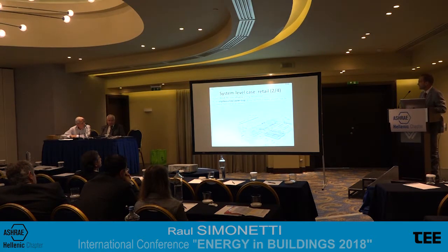If you break up this cross-influence between the display cabinets and make them independent from each other, then you can get some additional benefits. First of all, of course, the heat will have to be rejected using a medium. That can be a water loop. So there will be some water moving across all the display cabinets, accepting the heat that they reject, and then the heat is rejected by a chiller, or by using free cooling or a dry cooler, something like that. But the display cabinets will become independent from each other at that point.